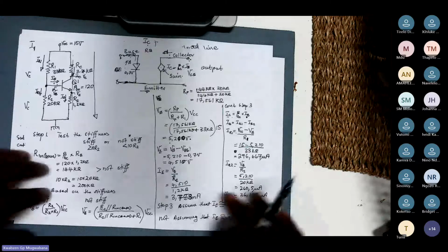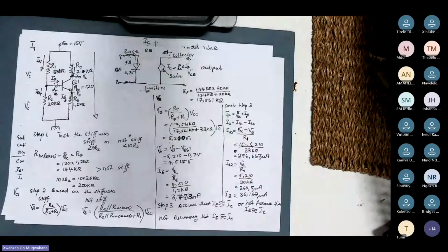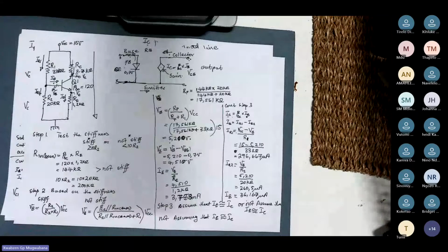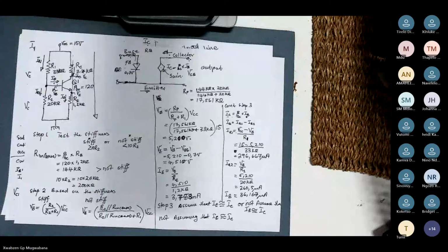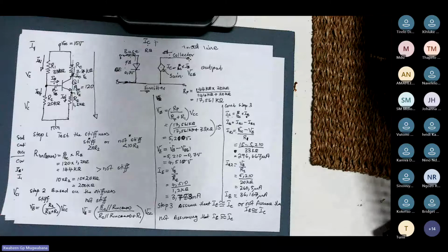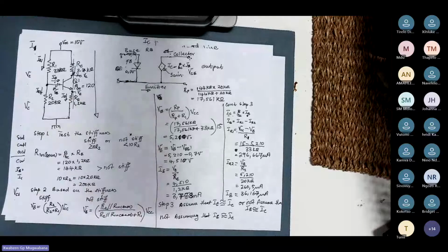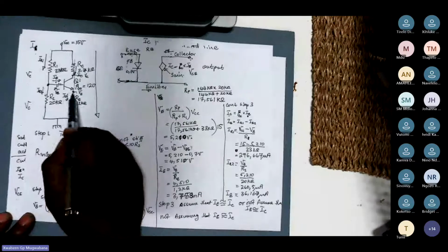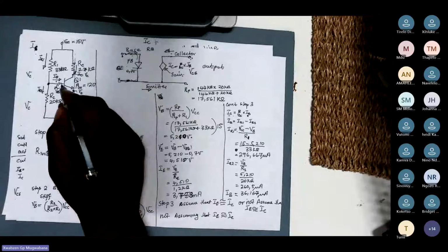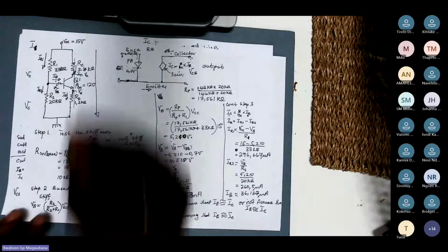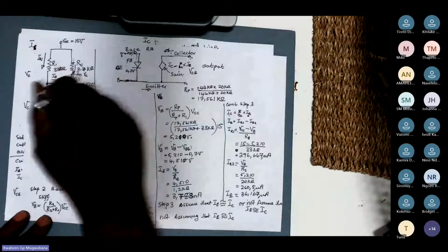Yes, sir. Now, this whole equation, what we have done, now we have calculated that this transistor of ours cannot give us a specific result because it is within the region of saturation. Remember, for the transistor to go into active mode, your collector to base junction must be reverse biased and your base to emitter junction must be forward biased, so that you can have the results of the collector to emitter there.